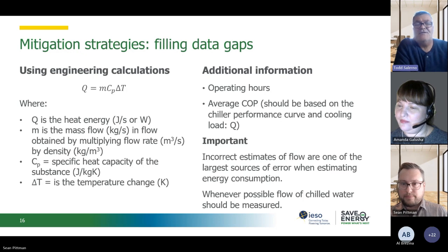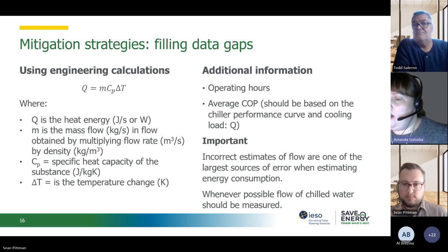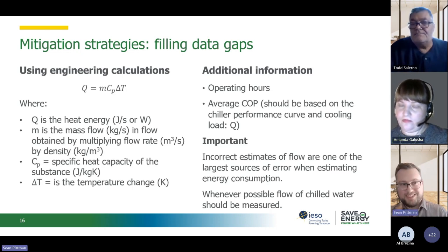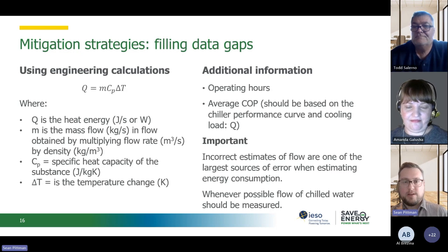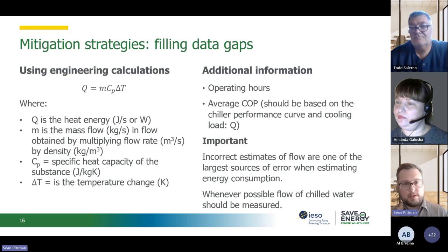I guess there was another question there too about ultrasonic metering, which was a good question. Yeah, this is a good one, and I think it's probably applicable to answer it now. The question is CHW flow rate is rarely measured. Is it common practice to do ultrasonic clamp-on meter measurements if possible? Yes, yes. If you can do a clamp-on meter to measure the flow rate, by proxy, that's definitely seen that applied lots of places.